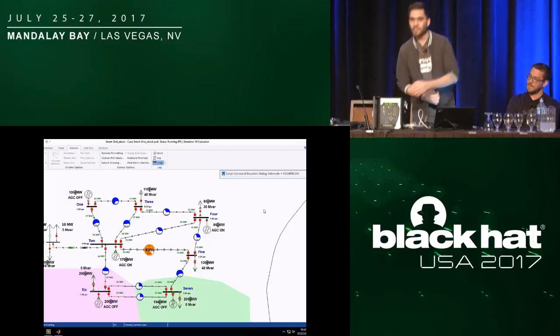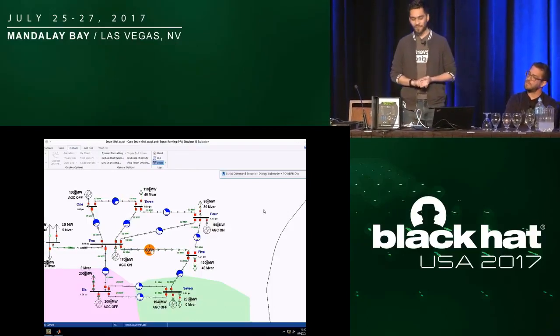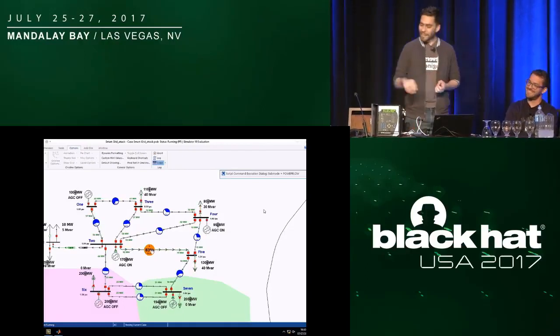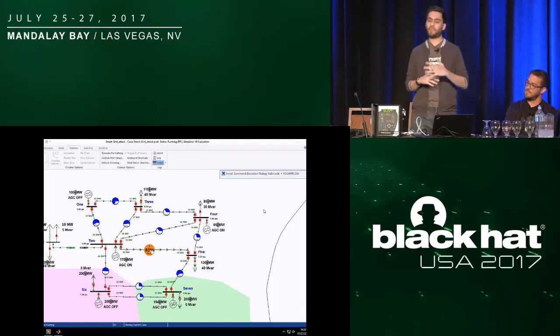I don't know, probably it's more visible that a green light is now on instead of a red light. It's like the opposite of traffic lights. A red light is good, the green light is bad. Green light means open breaker. So now the breaker is de-energized, so electricity is not flowing.